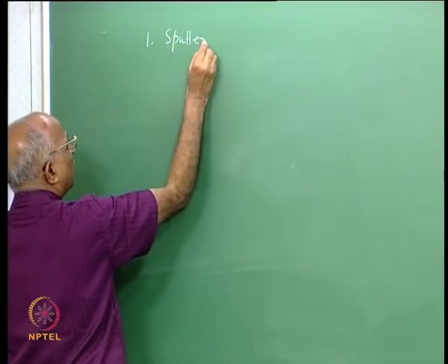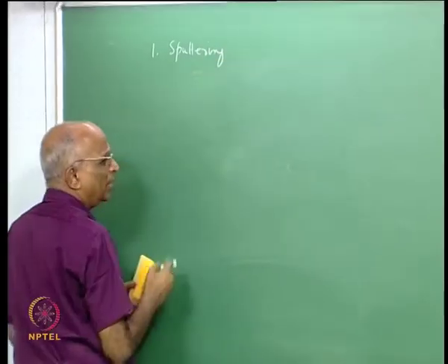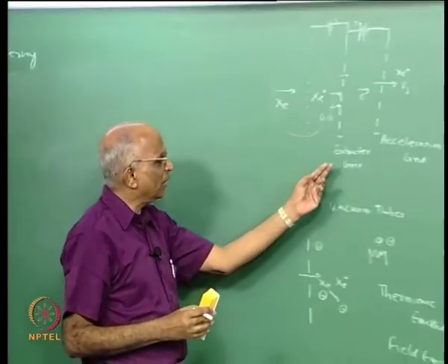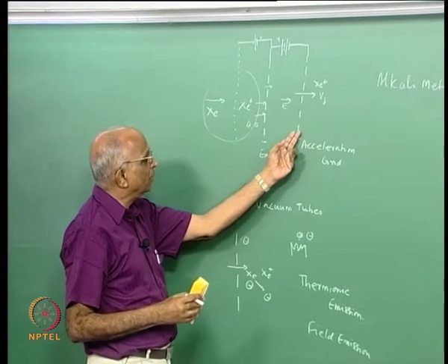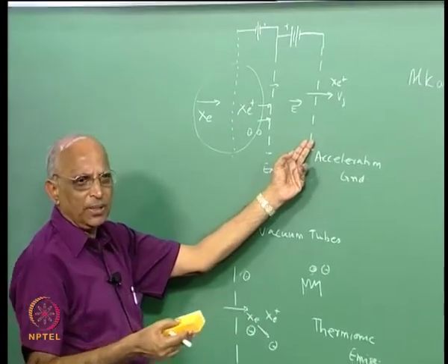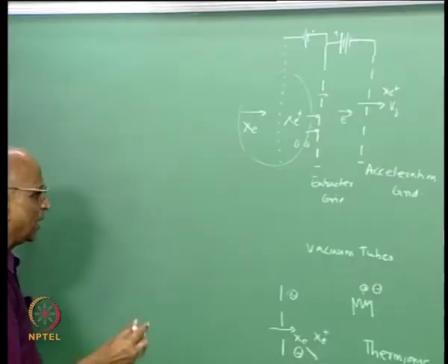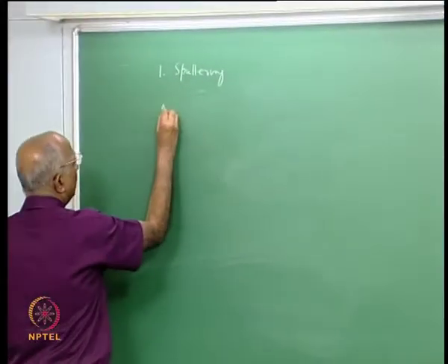But how do you correct for sputtering? Maybe I can only reduce it. I use something like, instead of using tungsten, if I use molybdenum, it is less susceptible to sputter, and therefore I use something like a molybdenum grid.